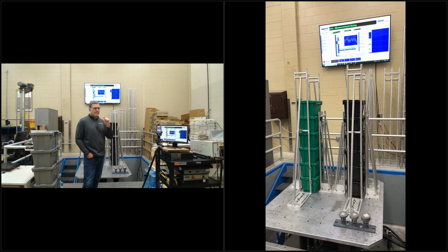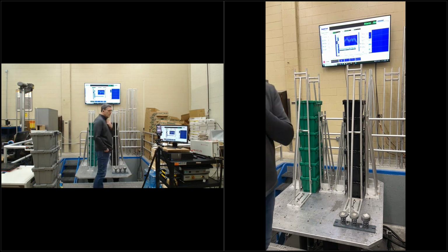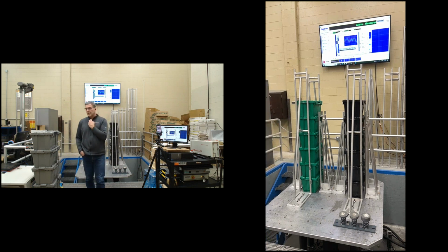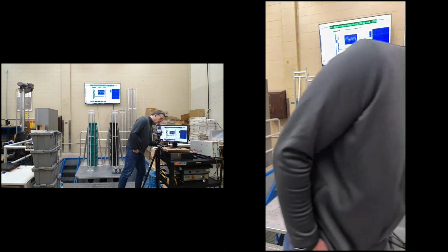It's really a response of the accelerometer on that tape. So you want a good solid mount. You know, glue is about as good as it gets, but it's glue. So, if it's super glue, it can leave a residue that's a pain to get off of the base of the accelerometer. They make, just so happens, I have a little stud here.